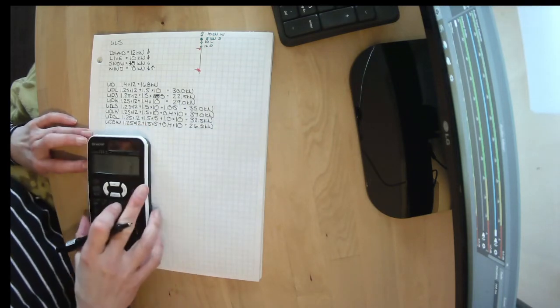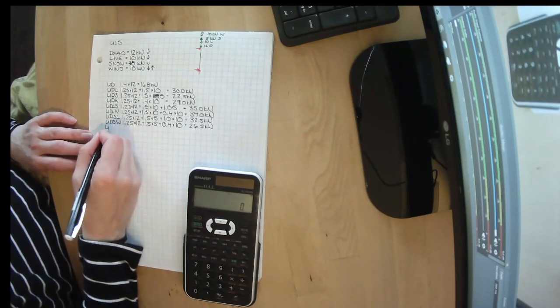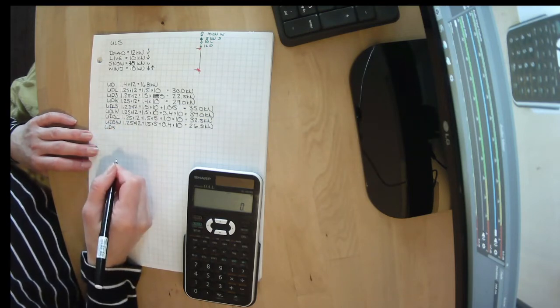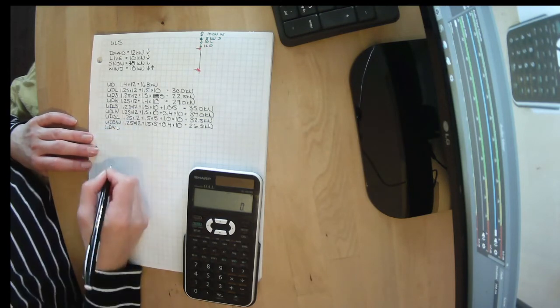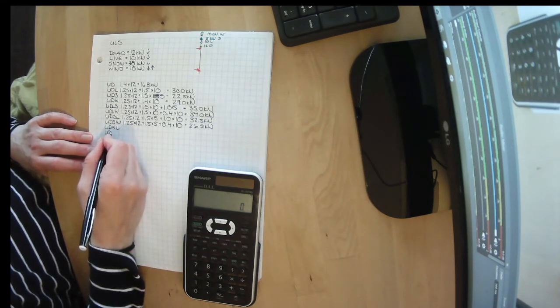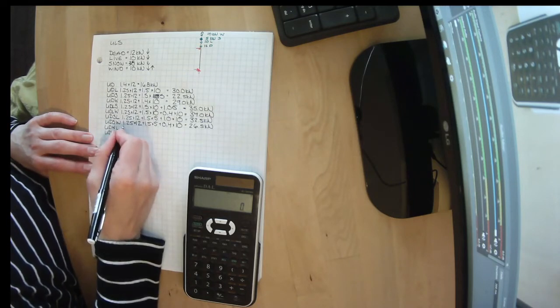Now we still have the possibility of wind being our principal load. So ultimate limit states, dead load, wind is our principal load, and live as a companion. Or ultimate limit states, dead load with wind as the principal load and snow as the companion load.